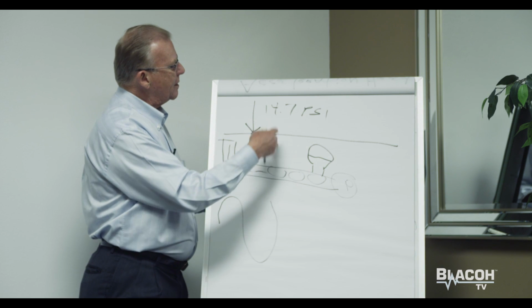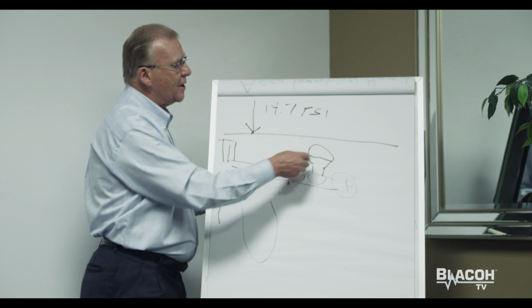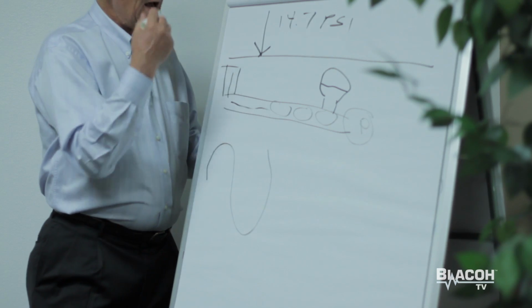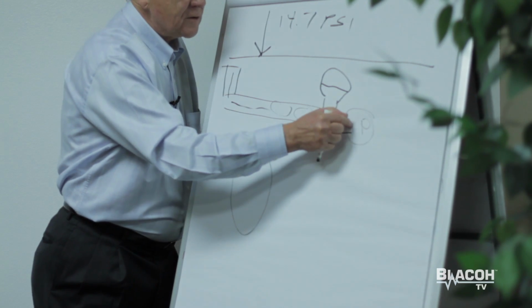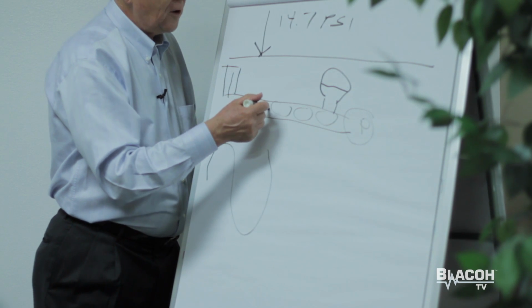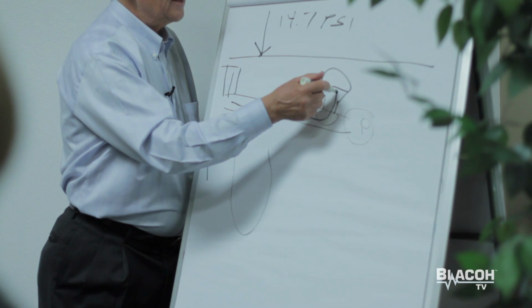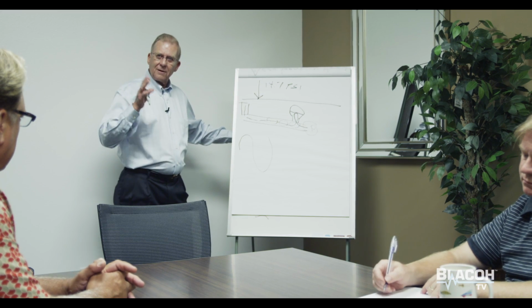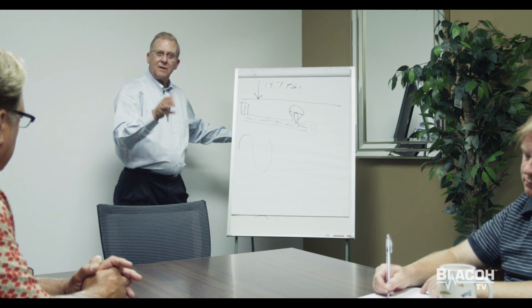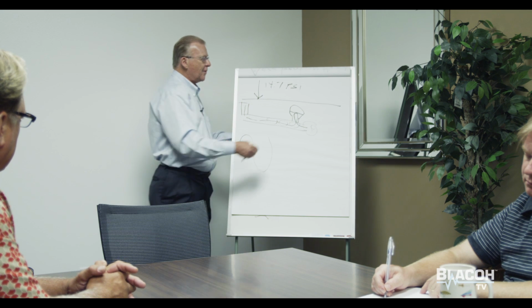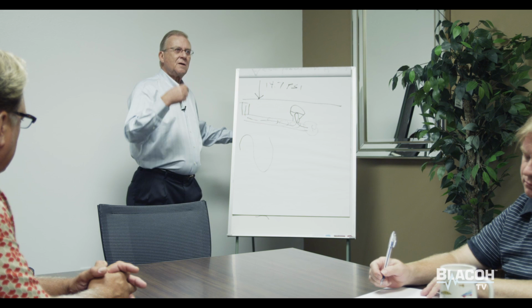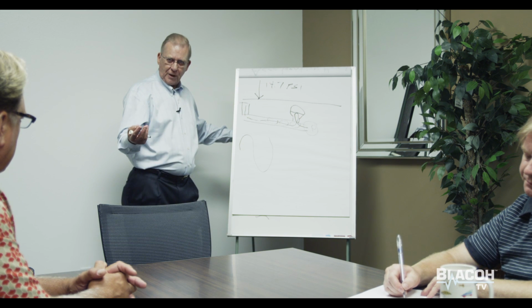And as I said, depending upon what the conditions are, we may actually pull a vacuum in the dampener. The idea is when these valves close on this pump, this flow, instead of stopping altogether, cycles up into here, keeps in motion like the car going around the city on the freeway, so that there is less energy expended when the pump shifts and the inlet valve opens to the chamber.